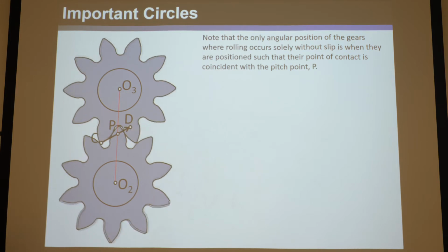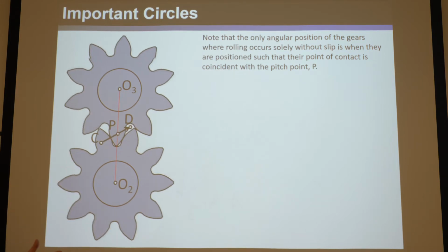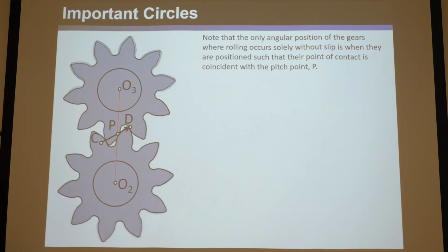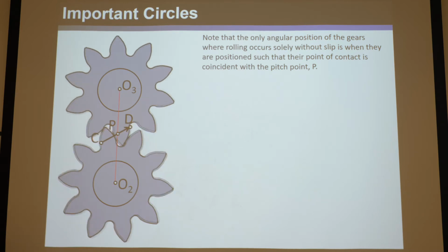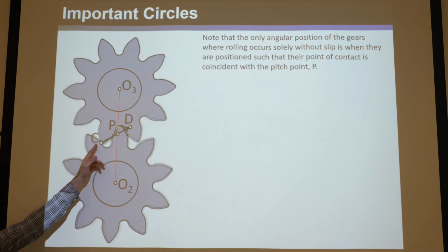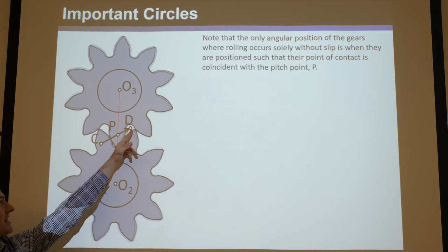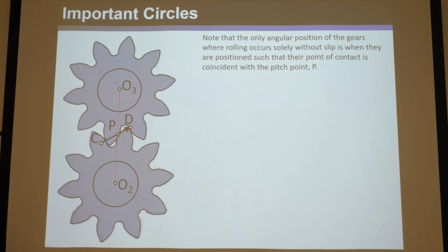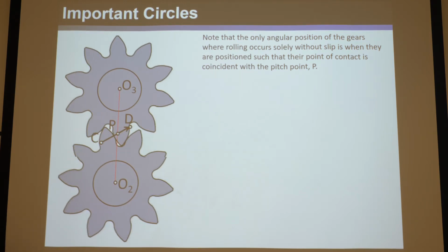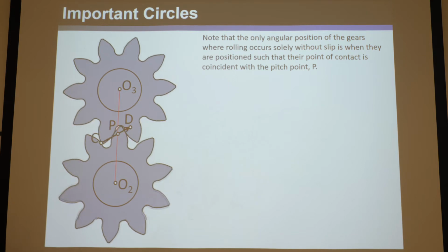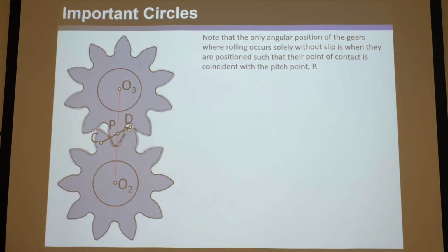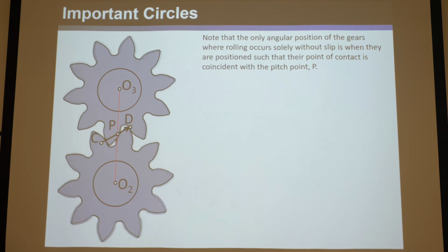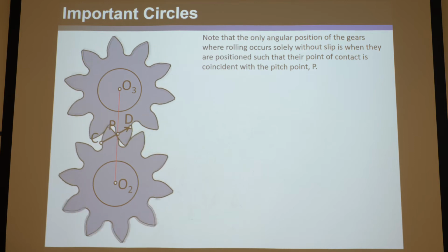If you put a ton of gears in a row, put a motor on one end, a lot of energy will be lost from the friction of the sliding teeth in that joint, and there won't be as much power on the output. That's because they're sliding and rolling from C to P and then from P to D. If gears were truly purely rolling their entire contact, then there would theoretically be no friction or extremely low friction, because no surface is relatively sliding if it's pure rolling, and they'd be very energy efficient.